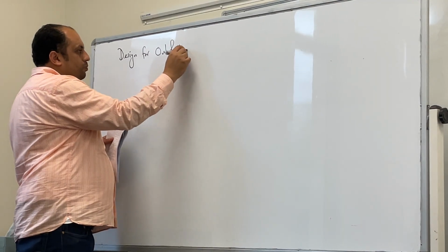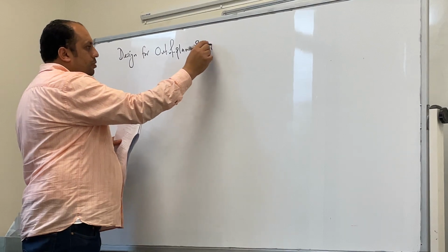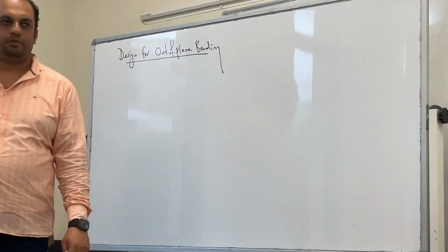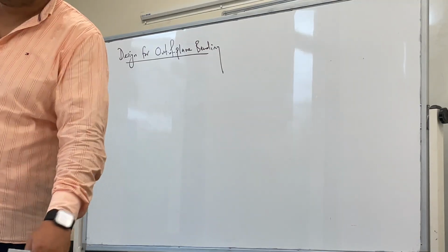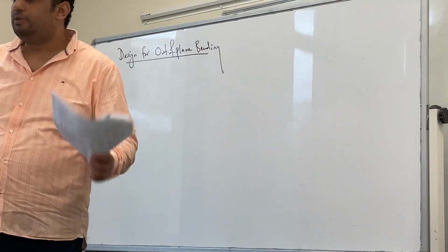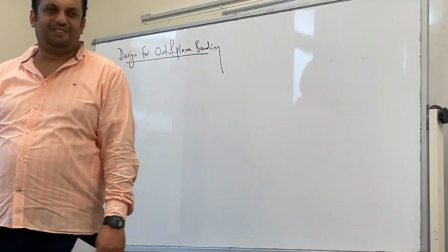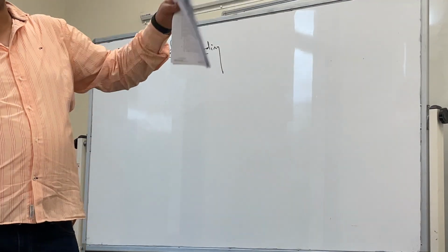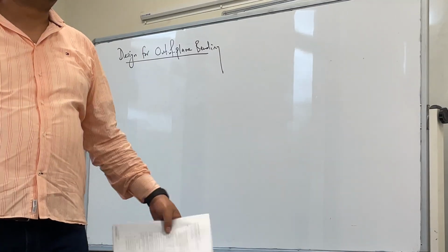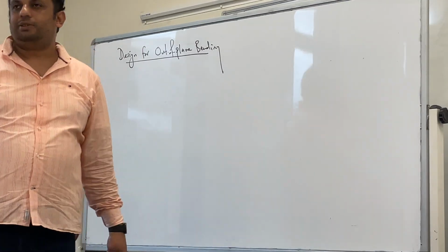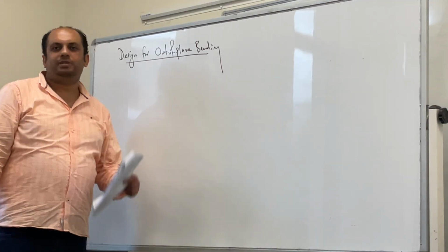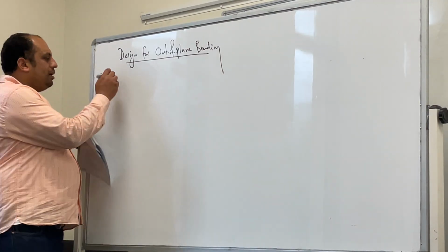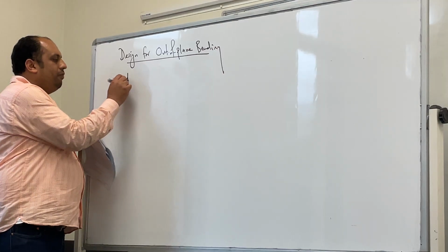So the out of plane bending would be on just the exterior of the wall, because the window will not get a side. But for out of plane bending, it doesn't matter. For the first part, because we have different axial loads, that's why we pick the critical one. But for the second one, the external wall will be subjected to the pressure. So they ask us to design for a wind pressure of what?